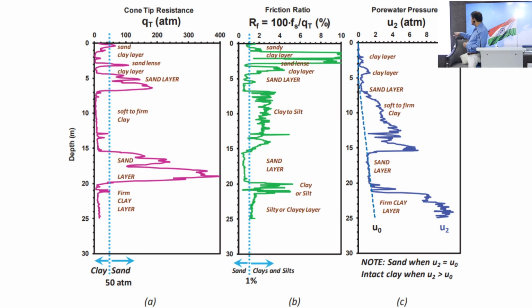And again you can see you have the dynamic and also static. That U0 is the static one, what you are getting from the pore pressure dissipation test, and the dynamic one. I think somebody asked me what's the real difference between dynamic and static. A good example is the difference between a seismic event and a normal event.